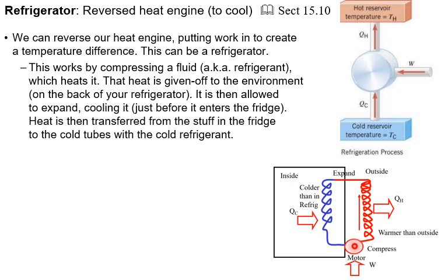You need refrigerant to do this. So there's a little motor compressing fluid and circulating it all the time. As before, this is still true. It's an engine, and therefore you're going through a cycle, and therefore the change in internal energy is 0, and therefore the net work is equal to the net heat added to the system. So again, the net heat is the heat from the high temperature reservoir to the engine minus the heat from the engine to the cold reservoir.